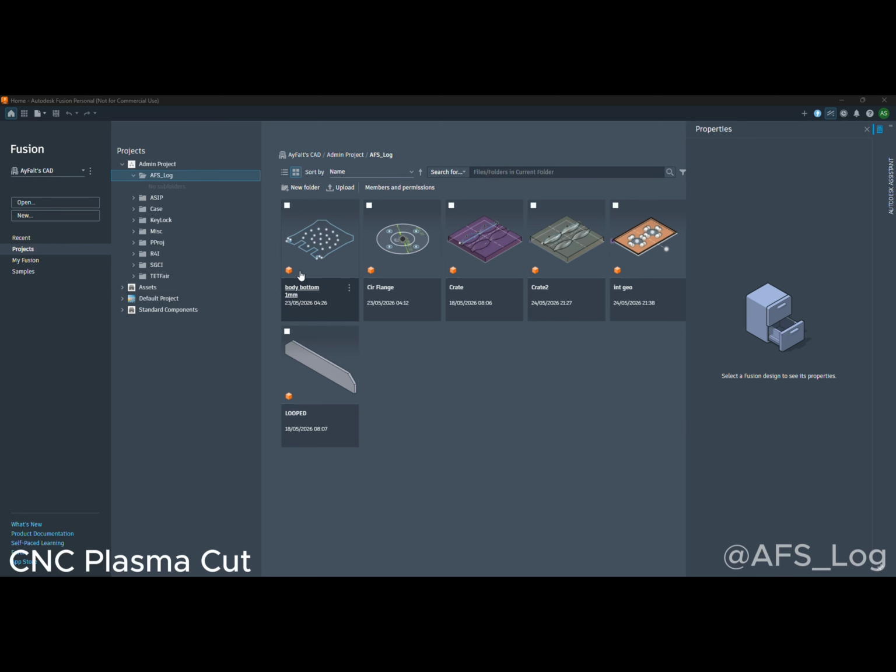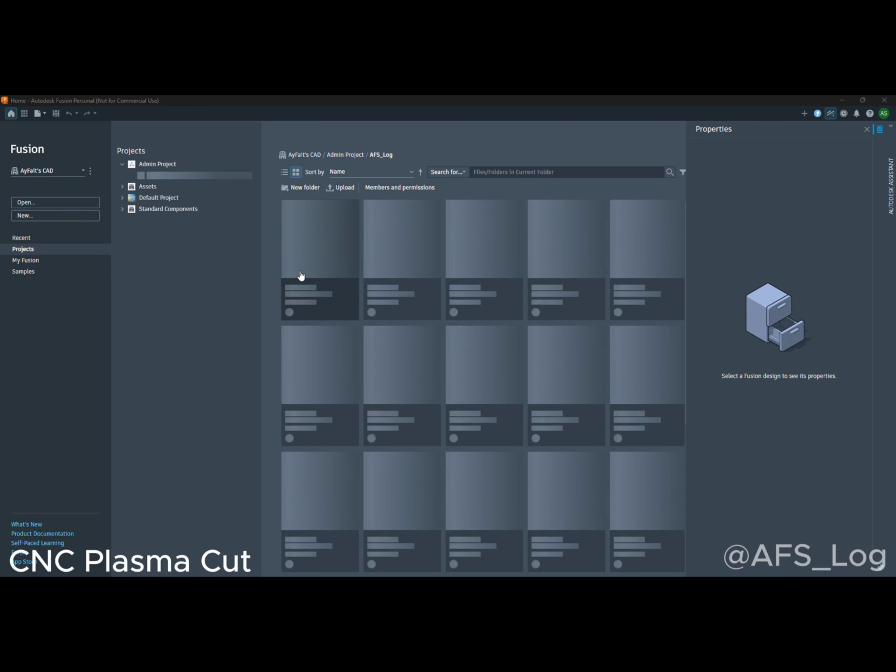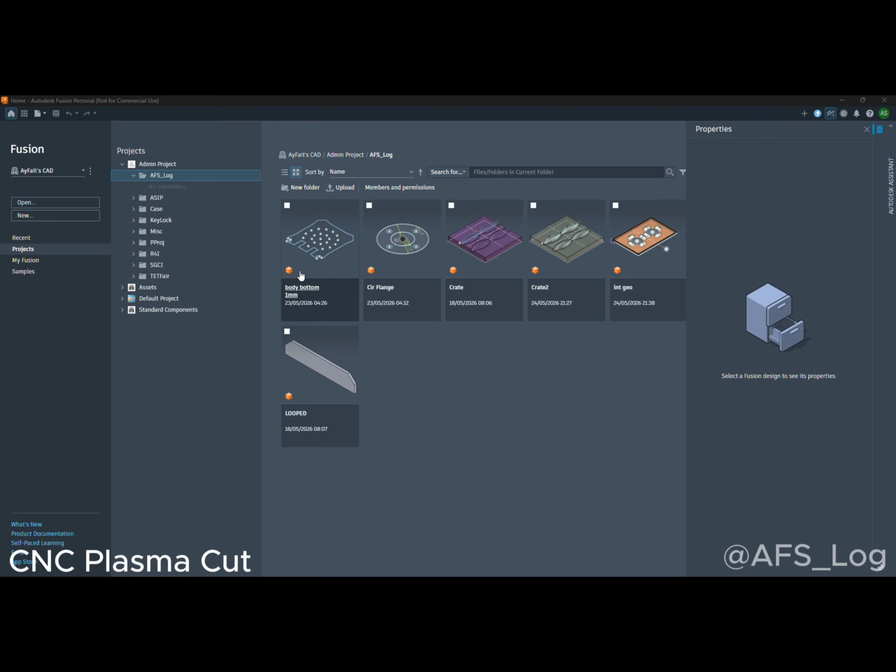First, there will be two kinds of profile I'll be talking about. First, I'll be talking about a profile that was designed on another CAD software like SolidWorks. Then the profile was exported as a DXF file. The profile was converted to a flat pattern, then projected for the sketch to be exported as a DXF file. Now the DXF file is imported into Fusion 360.